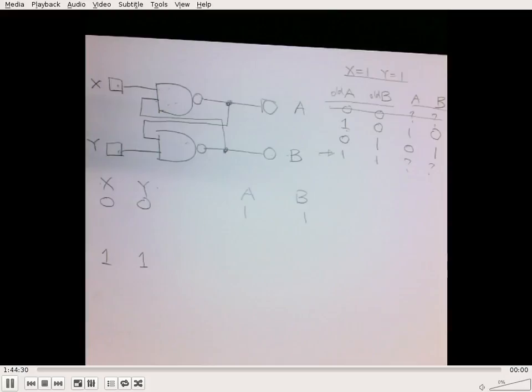Is it the luck of the draw, or is there some other factor that will determine, pretty much deterministically, which one is going to be a 1 and which one is going to be a 0? Be the length of the circuit? Yep, it's going to be the propagation delay. Assuming these circuits are not truly identical and symmetric, if one circuitry just takes a little bit longer to complete the calculation, that will determine which one is going to be affecting which other one. Okay, so the faster one is going to be...